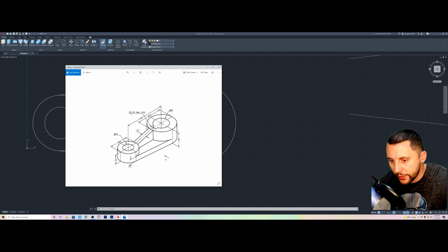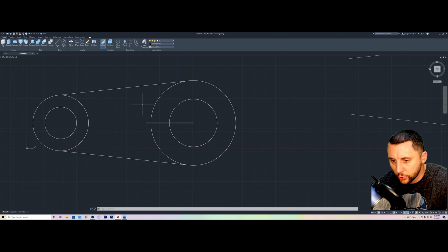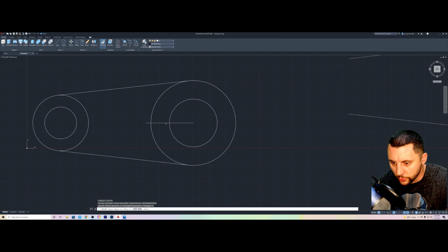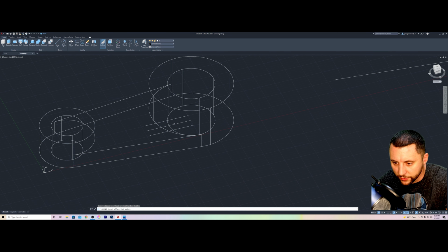All right, so the keyway is 12 by 6, and what you're going to do with this line is an offset of 6. You're going to go 6 up and 6 down. By the way, just make sure that we are working on the top surface, which I am not right now. You could work on the bottom because it's going to go through all the way, but I'd rather work on the top. So I'm just going to move this stuff from the bottom to the center of the top of those circles.